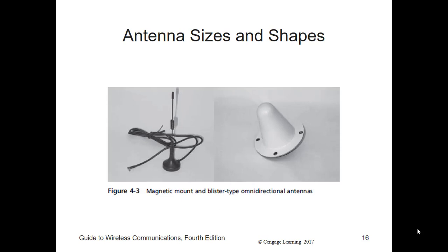When I did work for the police department, the vehicle computers were actually in the trunk, and we would plug that antenna into the computers in the trunk. But since the trunk was too well shielded, we couldn't get a signal out from the air card, so that cable would plug into the air card, and we would mount the antenna in the back of the car, and it wouldn't fall off because it was on there through a very strong magnet.